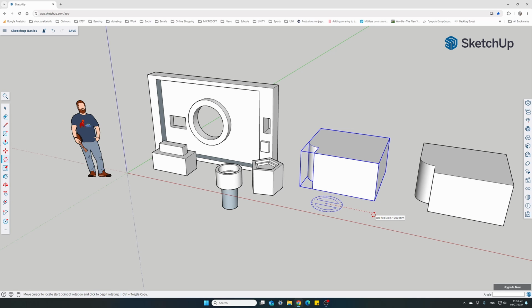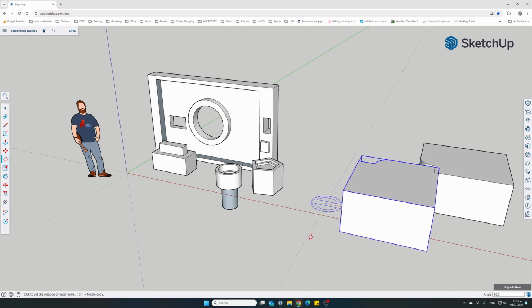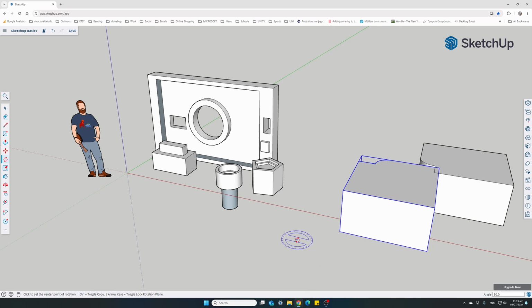And now we need to select 2 lines, the starting line and the angle we want to rotate it by. So I'm selecting here on the horizontal axis, click once, and then turn your mouse to the desired angle, or just type the angle on the keyboard, 90 degrees. You see that it rotates the object based on our rotation origin.